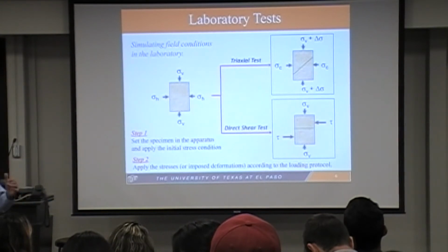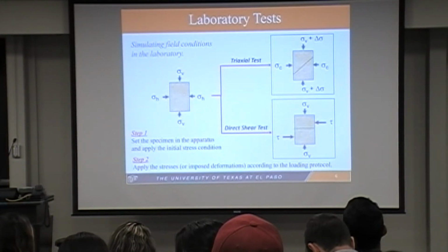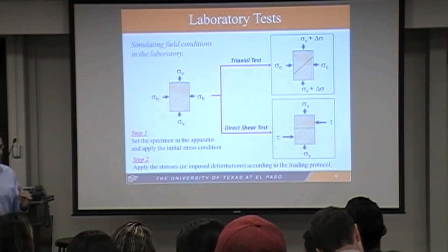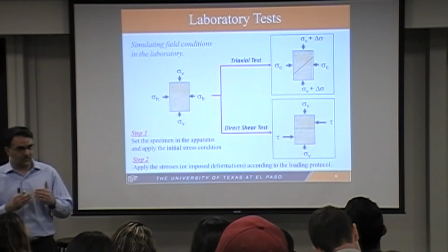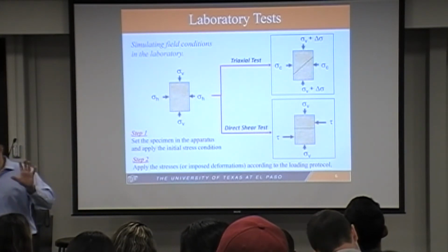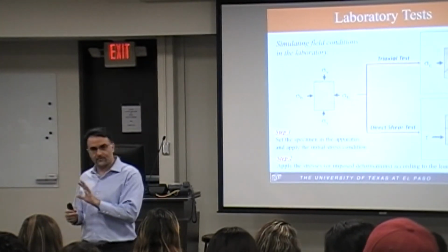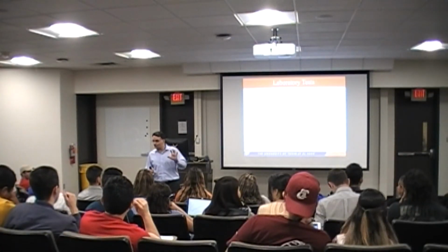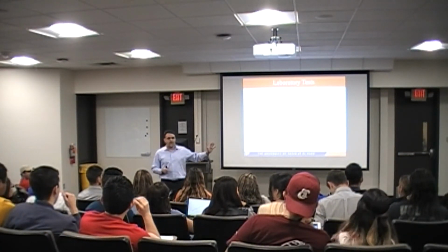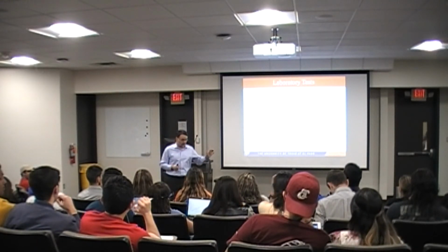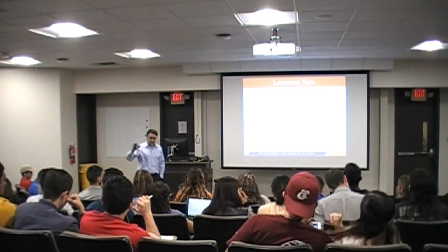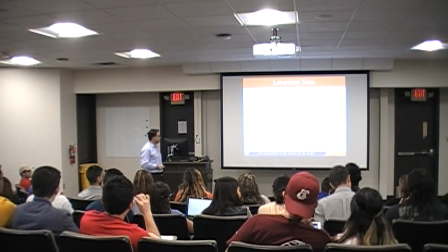So for the direct shear test, the way that we apply the confinement is based on the surcharges, right? The higher the surcharge, the higher the strength of the material, right? Because we had sigma in the general equation, tau equals C plus sigma times tangent of phi, right? And the higher the sigma, the higher the tau value. Tau was the shear strength of the soil, actually. And that was the equation of the line. Therefore, it falls along the failure line.